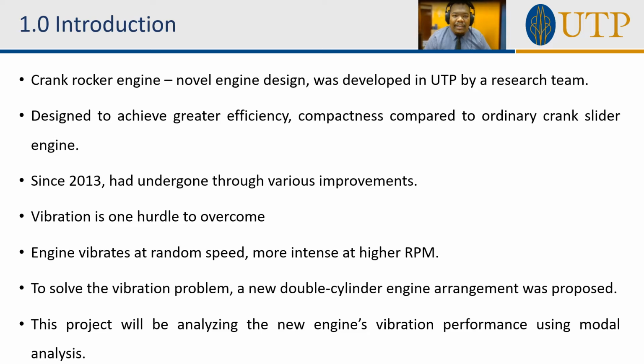The single-cylinder crank rocker engine vibrates at random speed, and the vibration intensifies as the RPM increases, and resonance occurred. In order to solve the problem, the double-cylinder arrangement was proposed, and this project will be analyzing its vibration performance through the use of modal analysis technique.